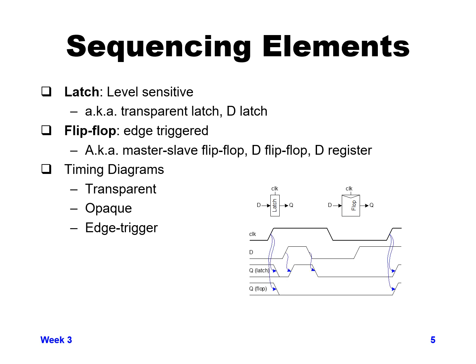So let's look at the timing diagrams here, and we can see if we had a clock switching like is shown and a data switching like is shown, when the clock goes from low to high, the latch decides, okay, I need to follow the value of D. I'm transparent and I'm open, and I allow the D value to come through.